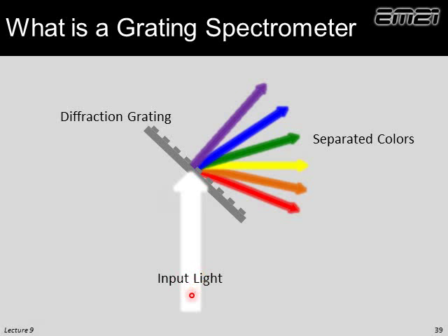And we've passed it probably through some sample. And the sample has perturbed certain colors and not others. And if we can tell what it's done, we could learn something about what we're sensing. So this broadband light that has passed through some kind of sample hits a diffraction grating, and it diffracts into some other direction. However, depending on the wavelength, that angle of the diffracted mode changes, because wavelength is a term that appears in the grating equation. So this grating disperses our different colors. So we can actually now detect the different colors separately and learn something about our sample.